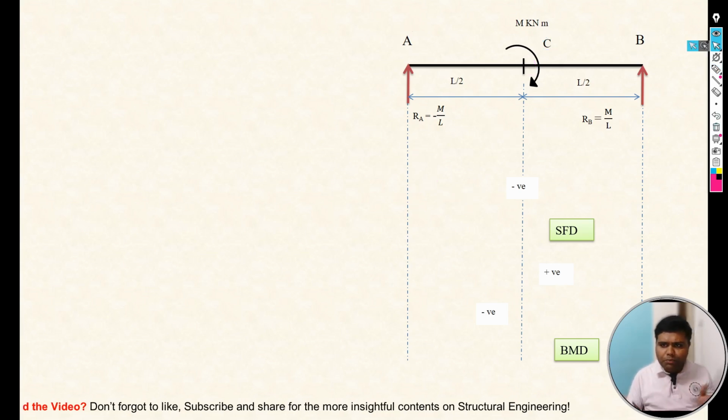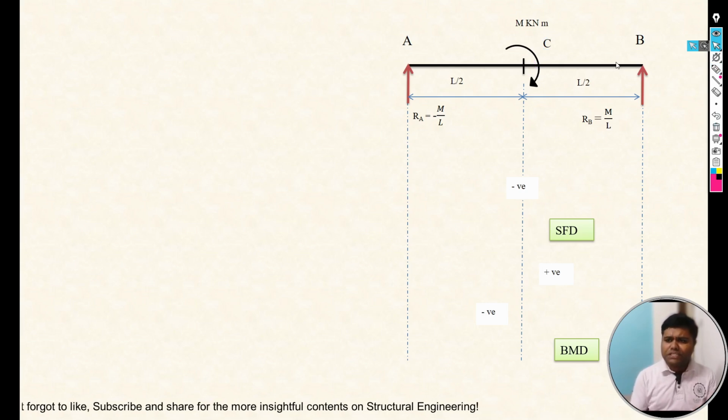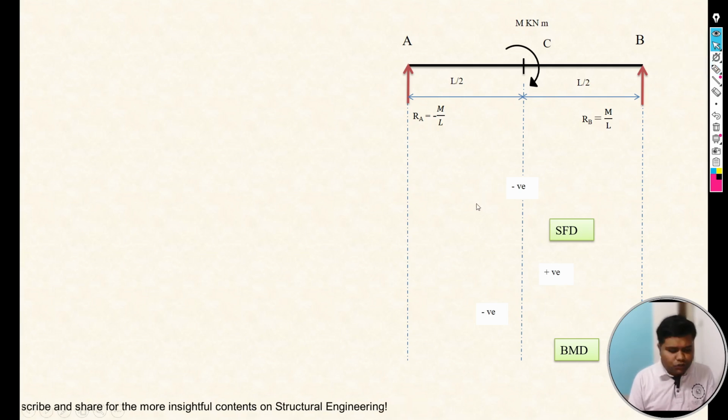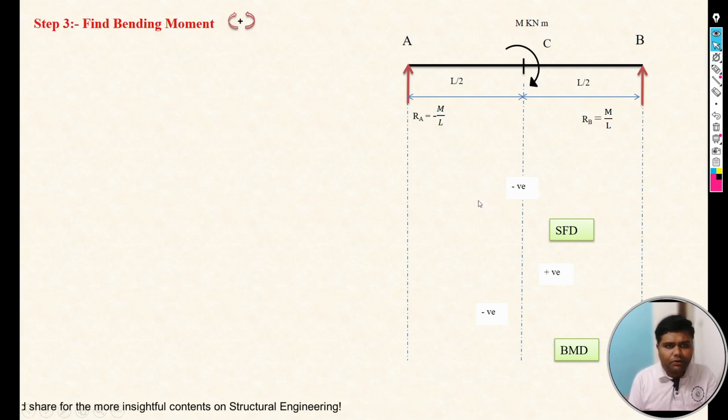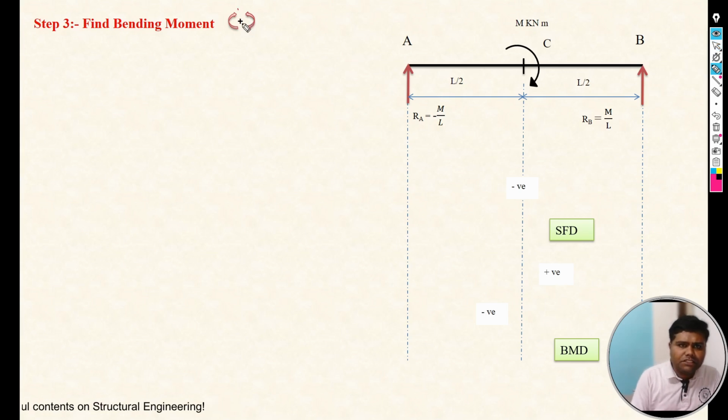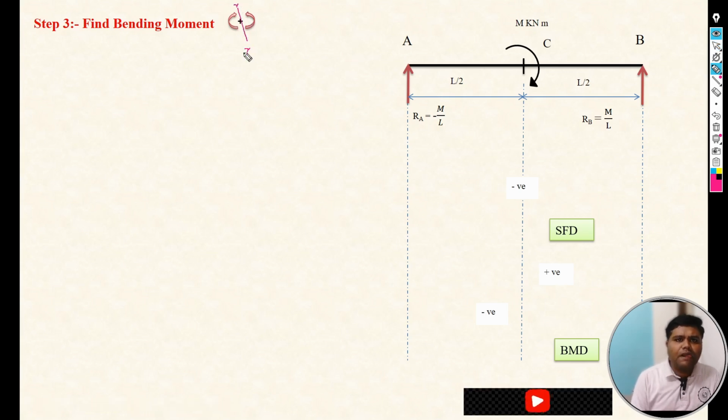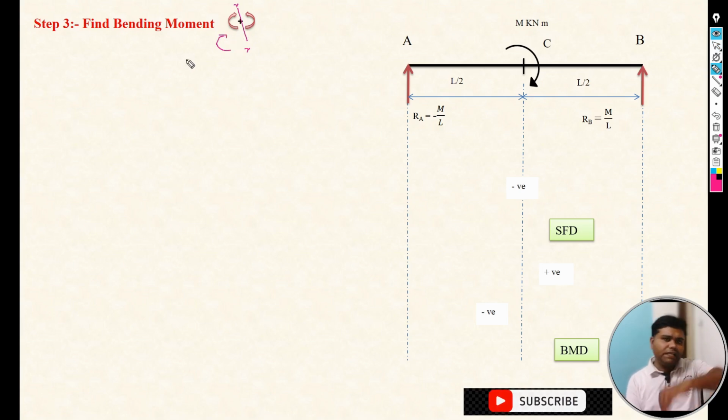And now all other points, let's say A and B, these are the normal forces acting at that point, so we can directly take the moment at these points. Okay, so first take moment at A point. The sign convention we have already discussed. Just take the section in between, and if any moment is clockwise on the left of that particular section, it should be positive.